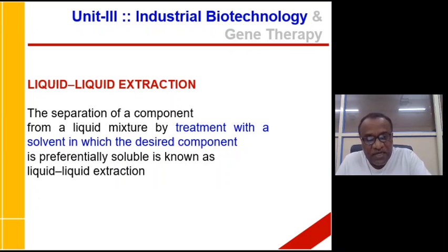You are extracting your product from the liquid mixture by use of another liquid or solvent wherein the product is preferentially soluble. It is already present in one liquid and you expect that it gets dissolved in another solvent. So this process is called liquid-liquid extraction.